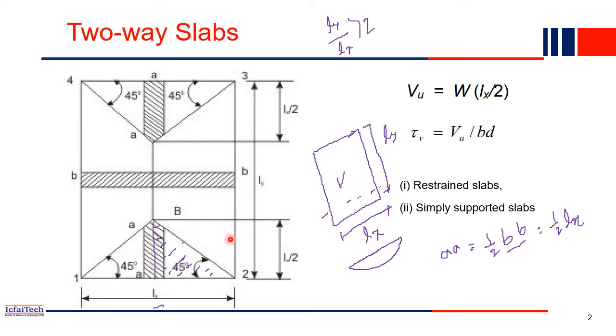Now let's understand the shear stress, where the shear stress will be maximum. As we have seen in the case of a normal cantilever beam, or simply supported or fixed, whatever the type of beam, shear force is always maximum near the edge, near the end of the support. Let me draw it quickly for your reference.